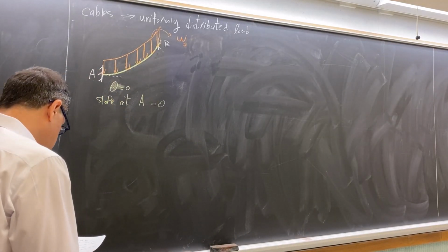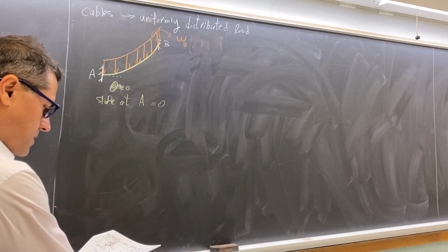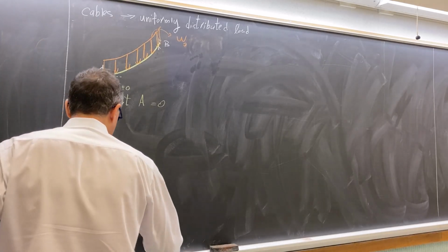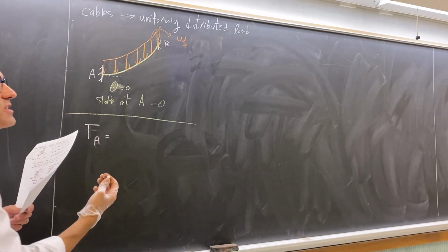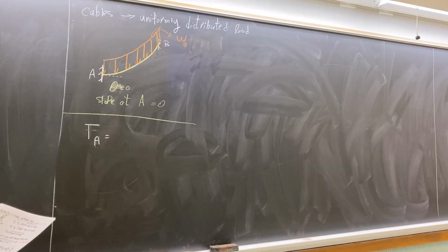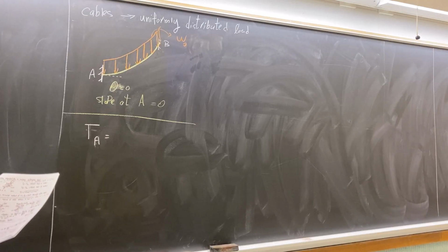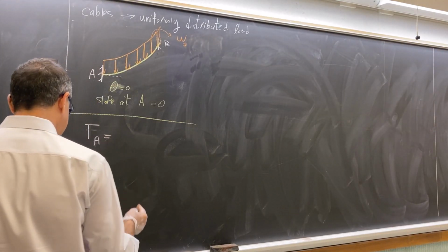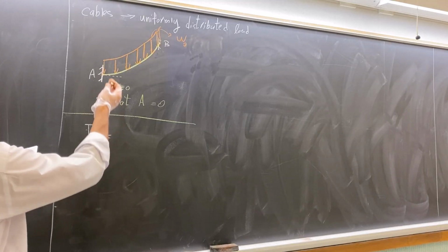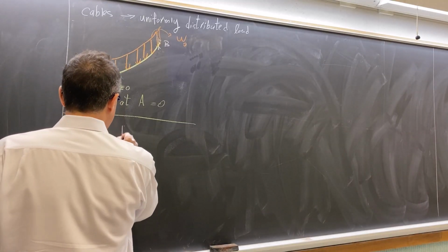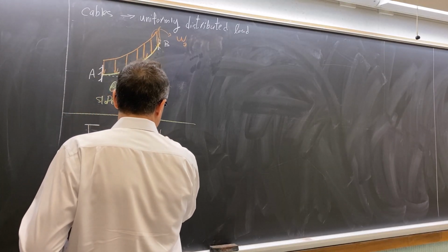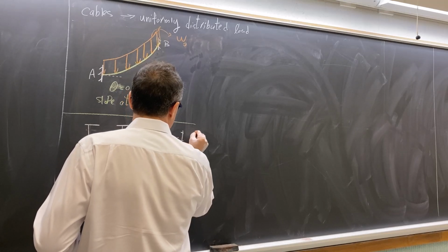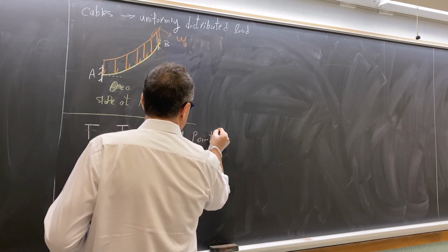We are going to cut. So if you look at point A, it is the lowest part of the cable. So it always has the lowest tensile force. So look at a cable. The lowest part of the cable always carries the lowest tensile force when it is under uniformly distributed load. So TA is T minimum, and it is the lowest point on the cable.